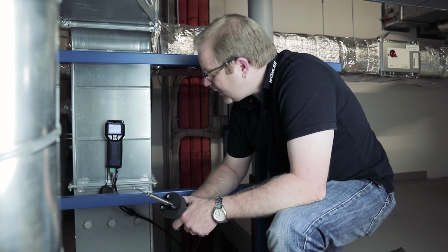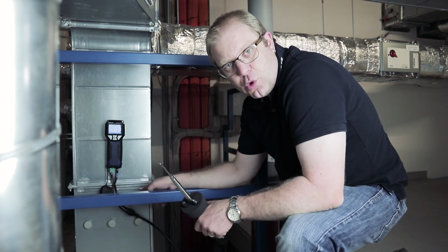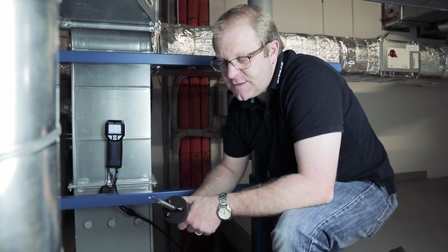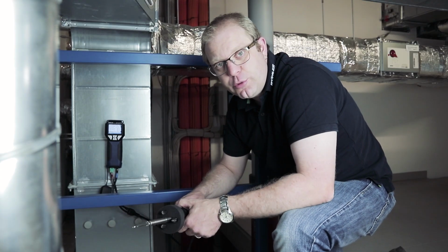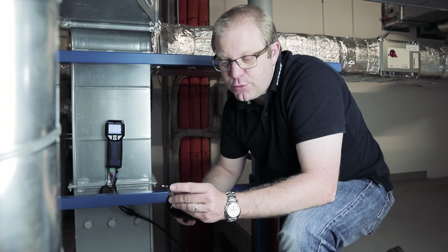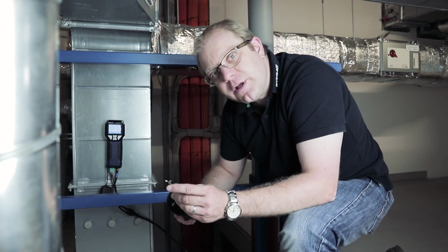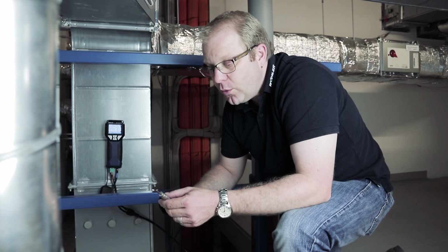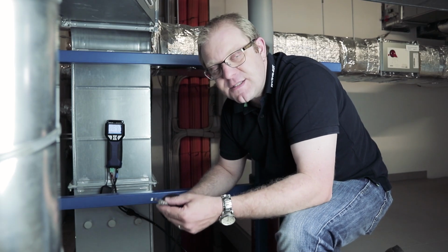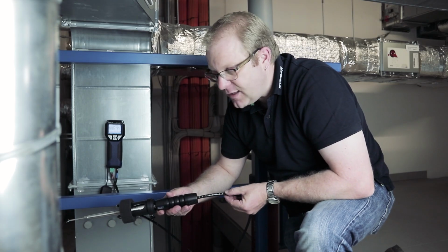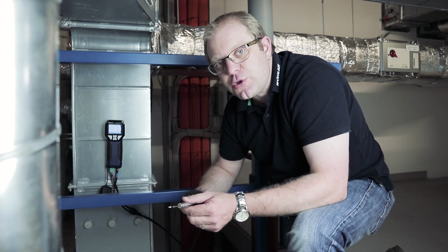In this ventilation system, the aim is to determine the partial volume flow in this line. To do this, I use the Wöhler DC 410 flow with the telescopic flow probe. This telescopic flow probe measures the volume flow via the differential pressure, in other words via the dynamic pressure and the flow pressure, and the area, so we move to several measuring points. The device tells me right here on the scale how far I have to push my flow probe in.